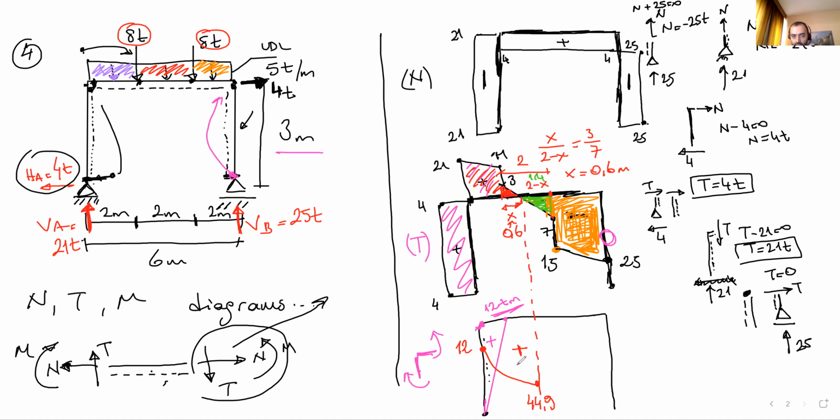44.9. So it's minus, we are at the top of the hill here. We are gonna go down to 0 because the calculated area is the same. At this portion, the total is, we are at the positive side, no worries. We go to this 0 point. This is the moment of the beam.